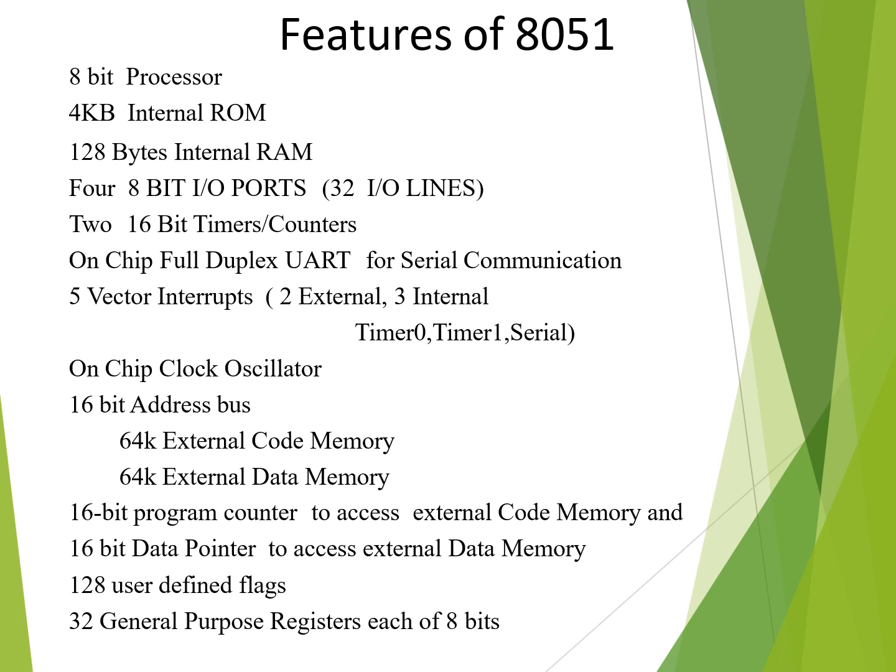Before entering into the 8051 architecture, just a recall about the features of 8051. So 8051 is an 8-bit microcontroller. It is having 4 kilobytes of internal ROM. It is having 128 bytes of internal RAM. It is associated with four 8-bit IO ports. It is having 2 inbuilt timers. It is having one serial communication interface.